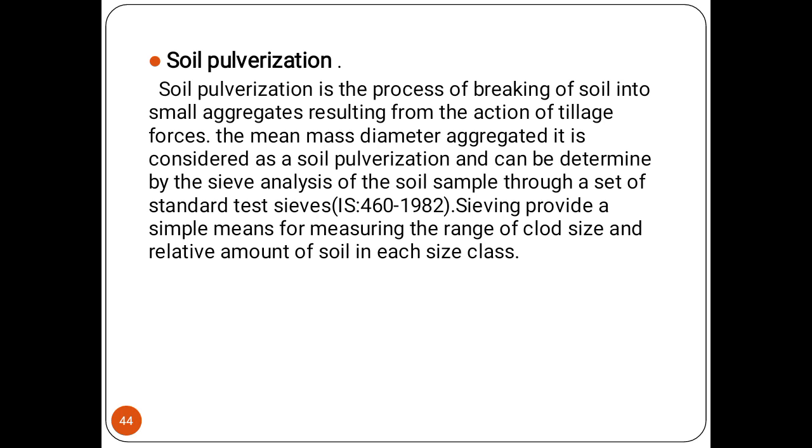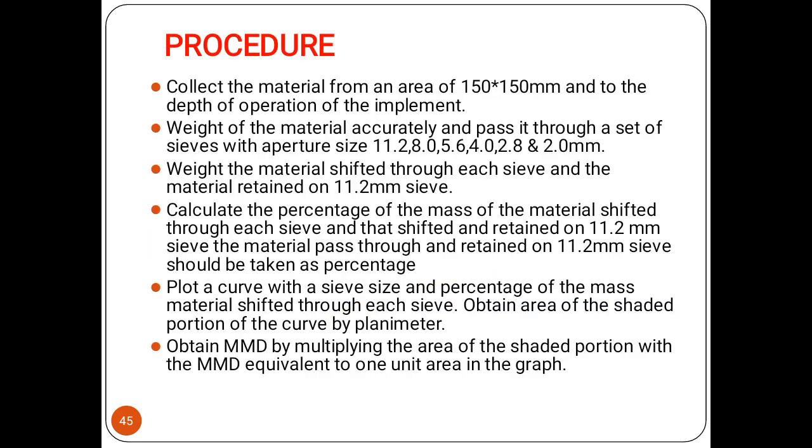It is considered as soil pulverization and can be determined by the sieve analysis method. Sieves provide a simple means of measuring the range of clod size and the relative amount of the soil in each size class. This is the procedure to find out the MMD: collect the material from an area of 150 by 150 millimeter and to the depth of operation of the implement.